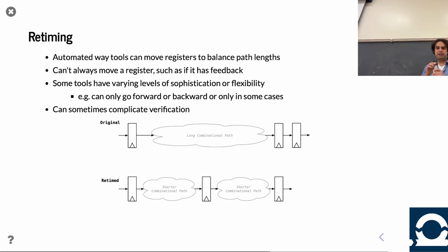The question about the verification and the LEC, the logical equivalence check, is that automated? It can be. A logical equivalence check, or LEC, is a key part of a lot of verification flows. Basically, you transform a design in some way, and you want to convince yourself that it's still the same design. So with a LEC, you put in design A, modify it, get design A prime, and compare the two to convince yourself they're still equivalent.